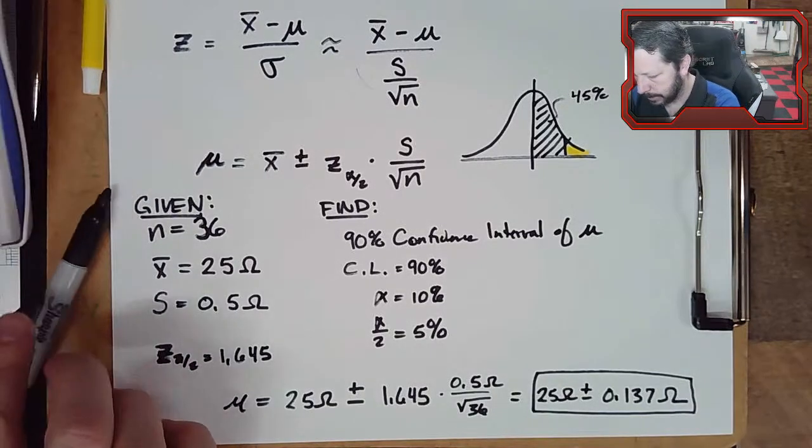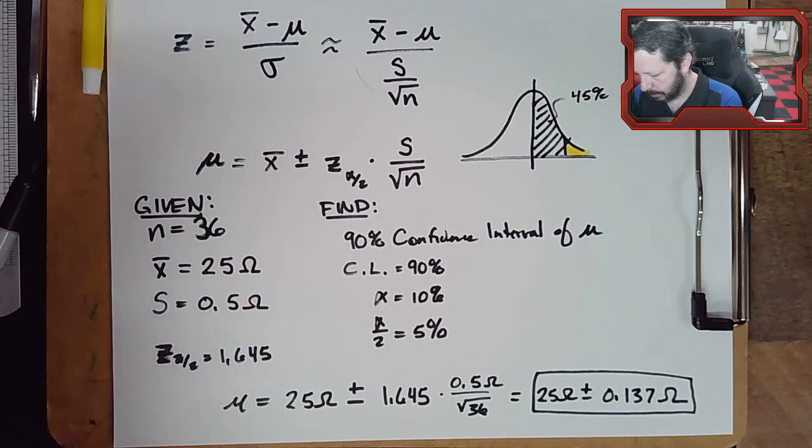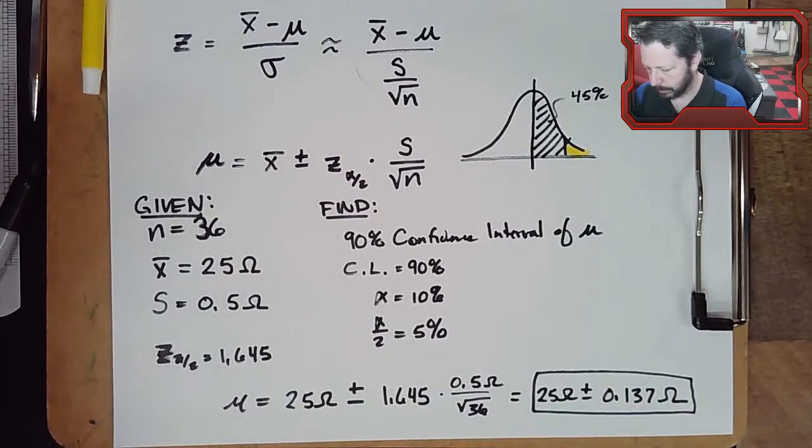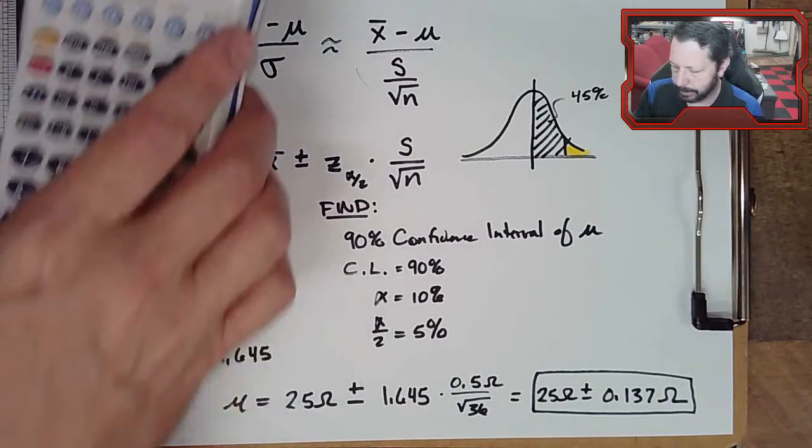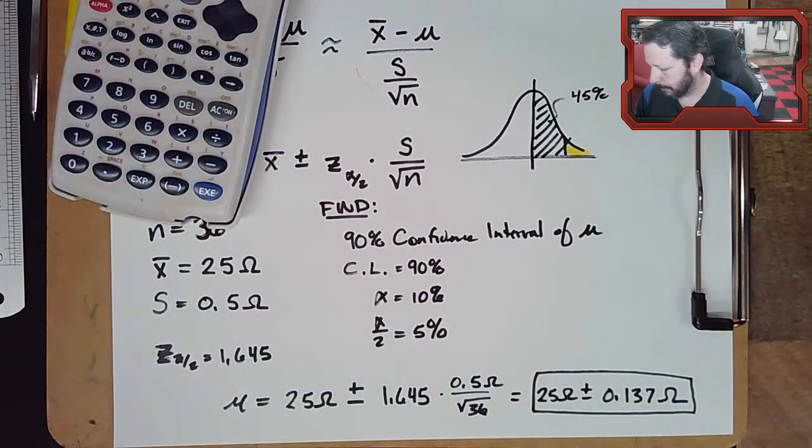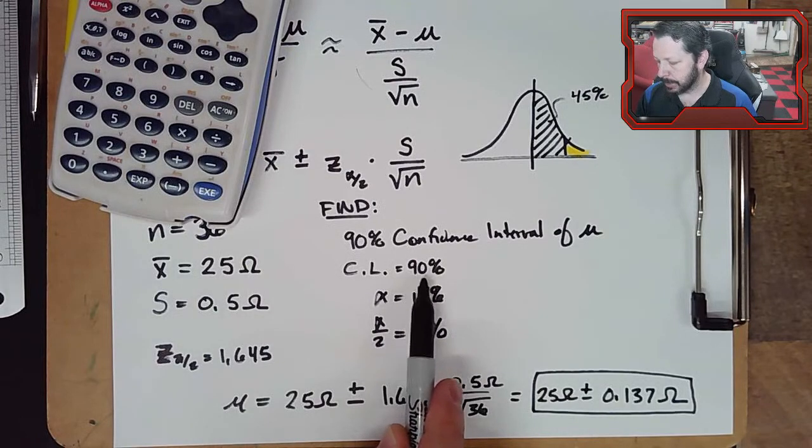That should be the tightest tolerance that they have, because 25 times, I think it'd have to be over 1 1/4 ohms for it to be outside of the 5% tolerance. So, and we could say this with 90% confidence.